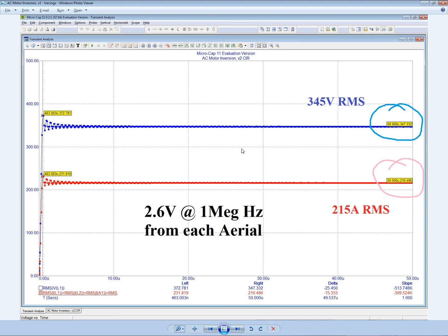It's remarkable what a resistor did. It smoothed out, and it accelerated the change in the beginning, and it depressed the surge. There used to be a humongous amperage surge, the red line here. It would go sky high into like 2 kiloamp range and then wiggle its way downwards as it was attempting to flatten out and drop. And then the voltage would not surge as much and would not take so long to flatten out in that sense, but it took forever to flatten out in the sense that it kept dropping.